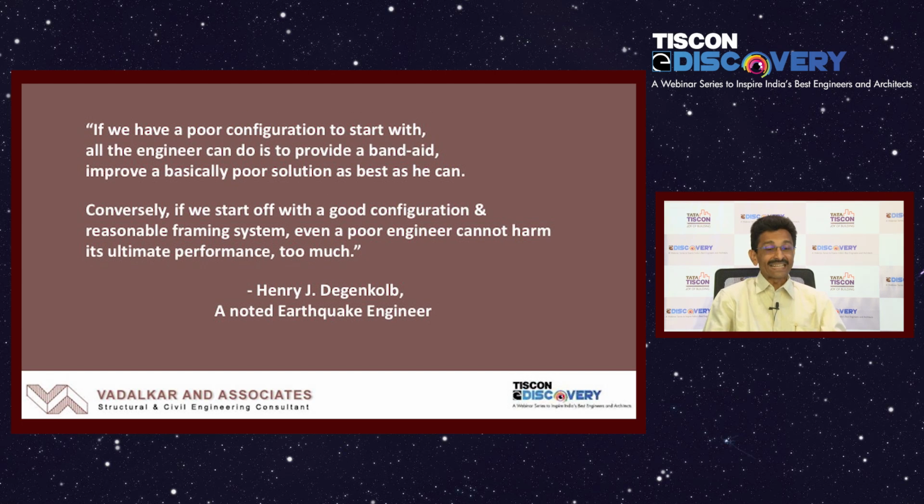Now I like this statement by a noted structural engineer, Henry Degenkolb. He says, if you have a very poor configuration to start with, all the engineer can do is provide a band-aid, to improve a poor solution as best as he can. But conversely, if you start with a very good configuration and a reasonable framing system, even a poor engineer cannot harm its ultimate performance too much. I think this is very important. We have to keep in mind that the performance of a structure depends on this fact.